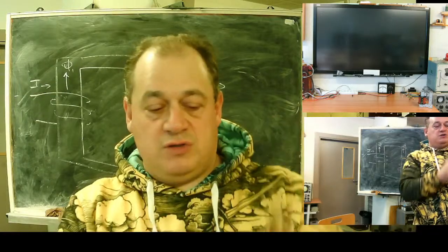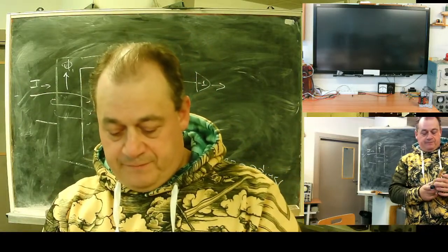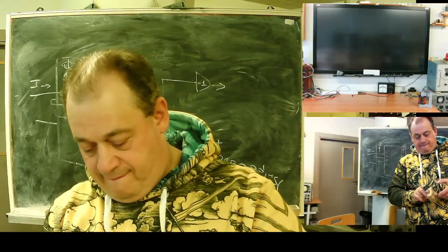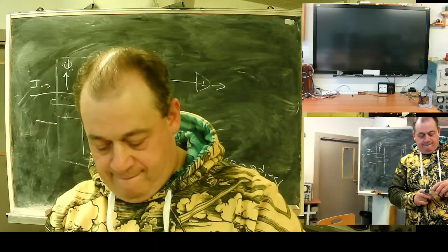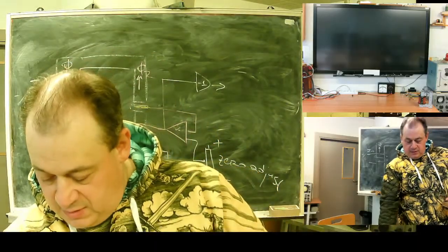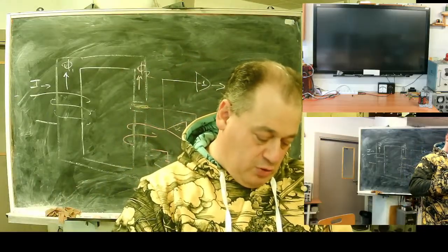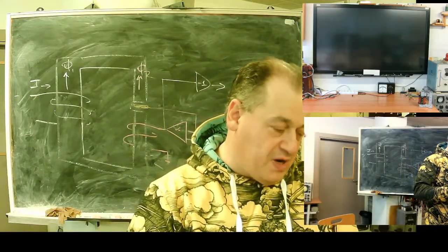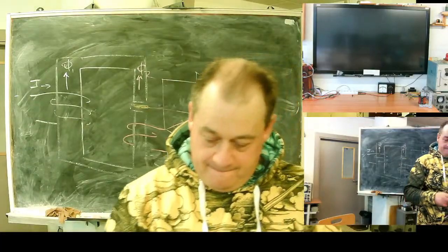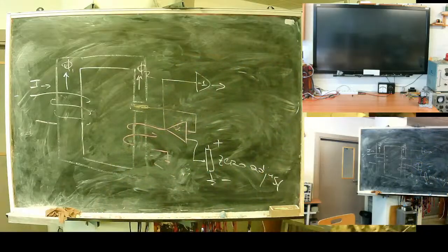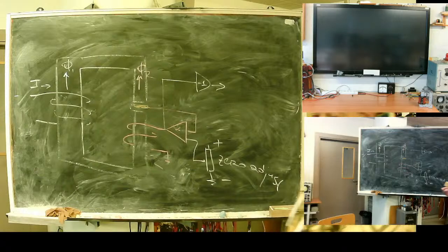This one is for zero adjust. Much better performance, because the Hall sensor always operates at zero. It's used to detect zero flux. It always operates near the zero point. So the non-linearity of Hall sensors has no effect here.